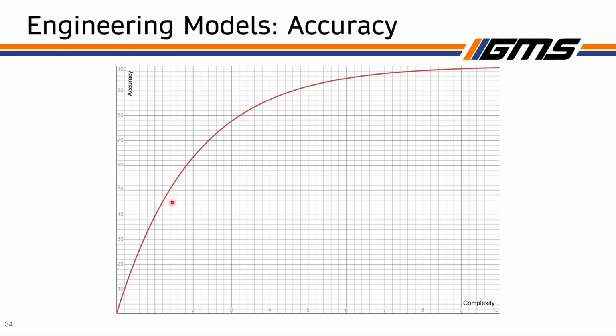But if you go a little bit more, to the state space quarter car, you can get a lot more accurate and get a much better look at how the car is going to behave. The state space quarter car, though, isn't even the most accurate way to do it, right? You can consider the fact that all of the corners of the car are going to be connected. And you can also consider the fact that the wheels aren't going to move straight up and down, right? They're going to rotate about an instant center, and your motion ratio might change a little bit, and all that kind of stuff, right?